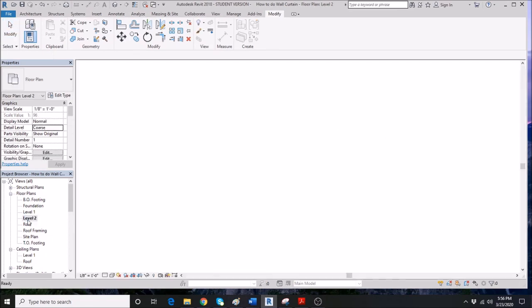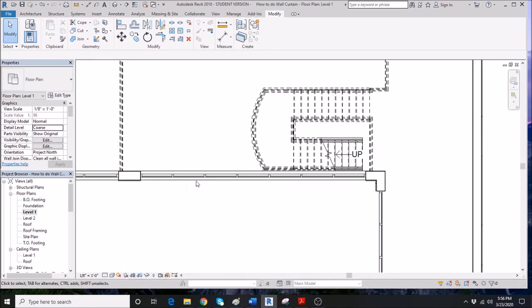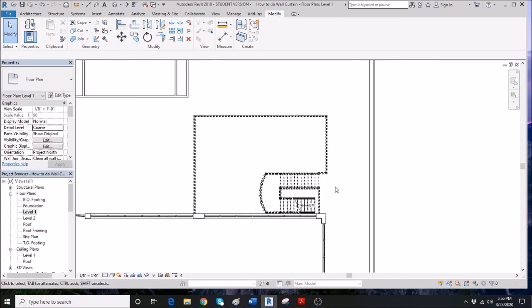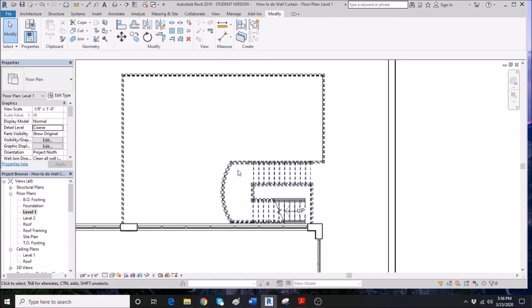So again, you have to begin on the first floor, roughly create the stair, and make use of the stair component. Make sure it is 9 feet, going up 9 feet 2 inches, and then go across. Click the second point, first, second, third point, and click.